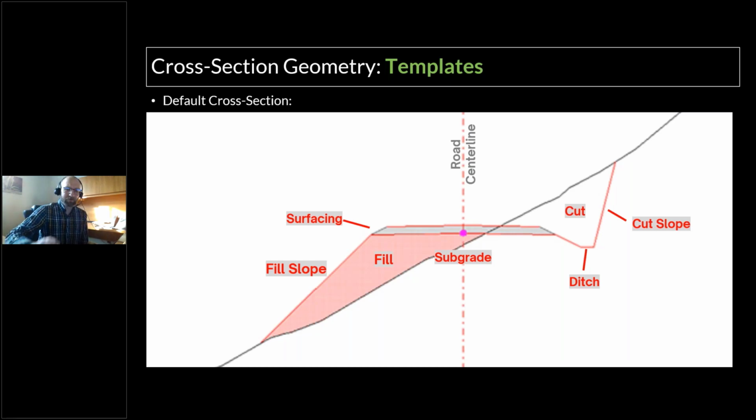From a user perspective, the templates are a collection of components. Those components are pre-built, available on our eLibrary or in the default templates that come with the software. If a user wants to deviate from those default cross sections, it's as simple as compiling the components they'd like into a single template and changing the parameters to match the dimensions and behavior they'd like.